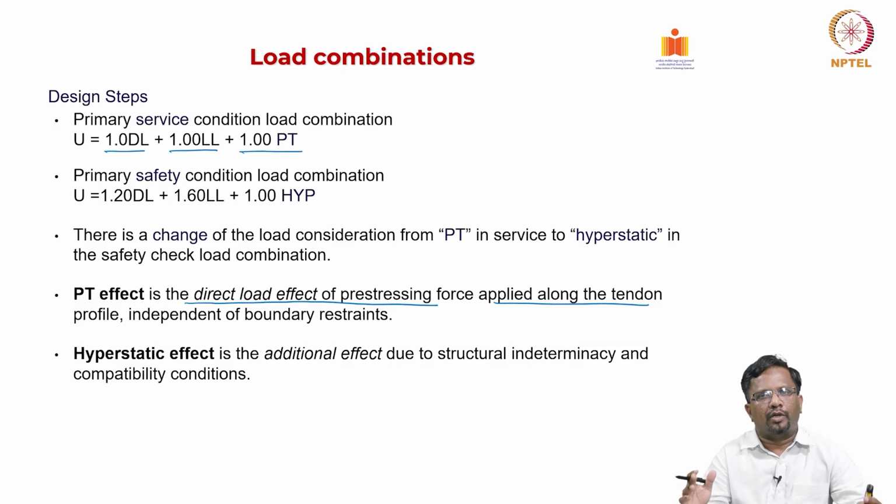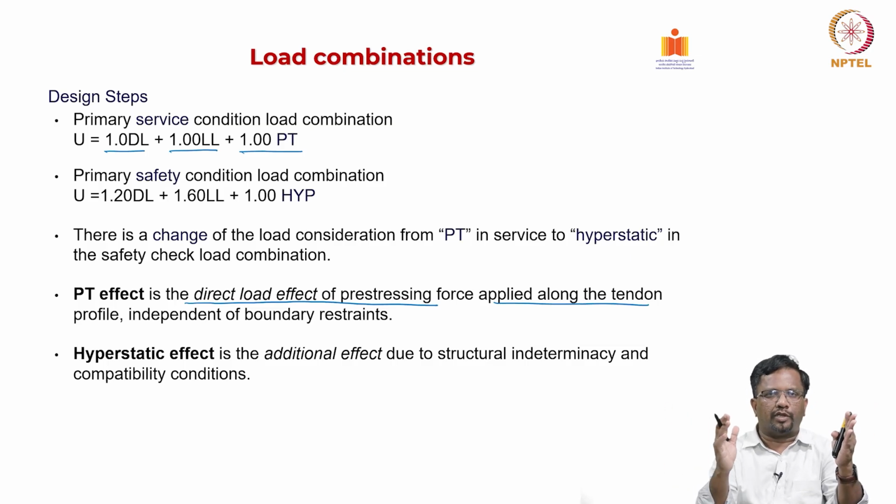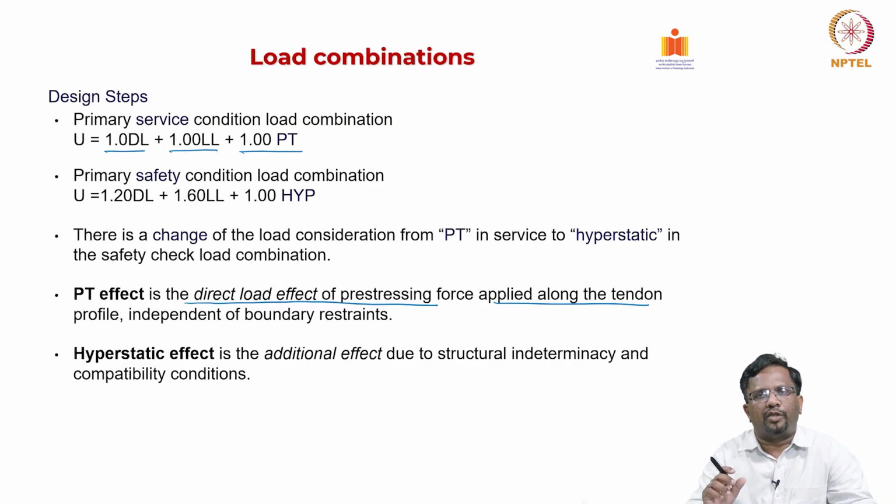That means the pre-stressing will induce a concentric pre-stressing force, and then if you have an eccentricity, that will also introduce moment. So, the pre-stressing moment and the concentric axial effect of the pre-stress have to be considered; that is called the PT effect.